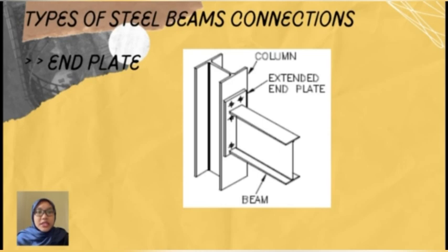And lastly, the end plate. This type of connection is made possible through the use of welding. The end plate is connected to the beam web through weld because its capacity and size is governed by the shear capacity of the beam web adjoining the weld. The load applied on the connection at the end of the member does not have eccentricities, so there are different types of end plate connection, including flexible, semi-rigid, and rigid end plate connection.